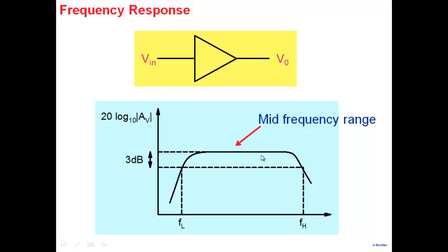So the useful range of an amplifier is this one here, the constant range, where the amplifier's response is frequency independent. Of course, there are places where you may be deliberately wanting this to happen. That's a different issue. You may want some lower frequency signals to be attenuated. If that's an issue, that's separate. But in general, if you want output to be a faithful reproduction of input, then you want to work in this range here. And this range is defined by two limits.